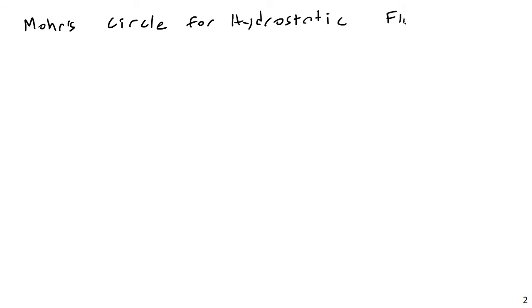And I can extend this even further if I draw Mohr's circle, if you remember from mechanics of materials, for the hydrostatic condition. For a hydrostatic fluid, the entire Mohr's circle is going to collapse down to a single dot.